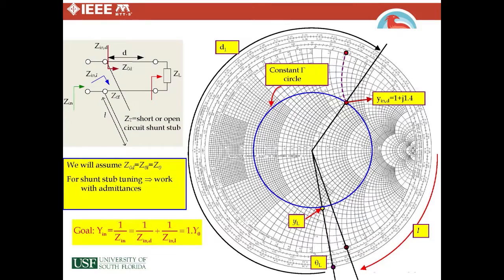Let's say that this one was 0.12 wavelengths. If I want to realize that in microstrip, which I don't have an example for, I'm going to use a microstrip calculator like LineCalc and figure out what length of line and width I want to use to realize that line of that length and that characteristic impedance.